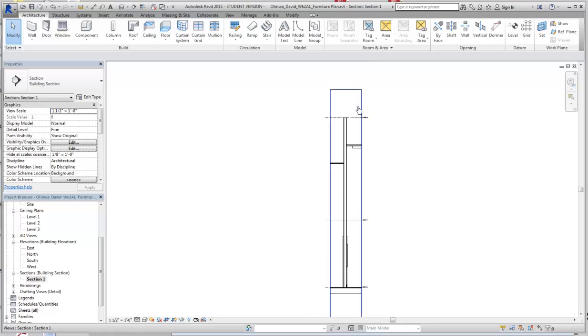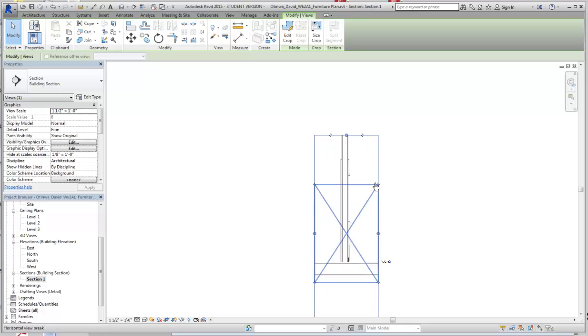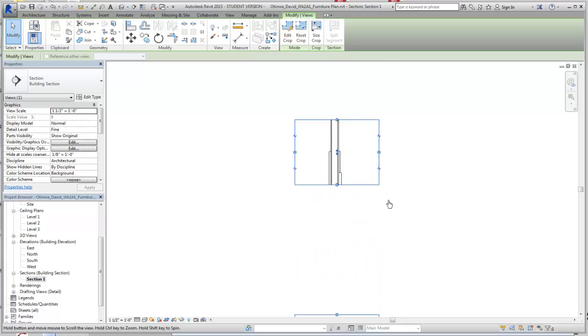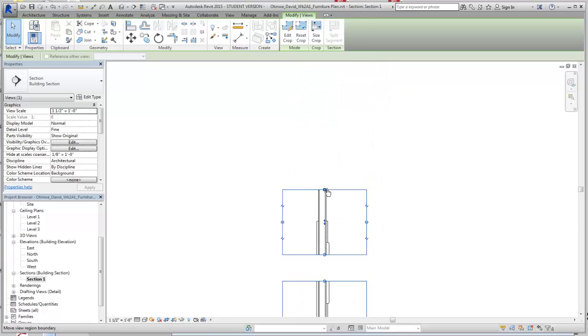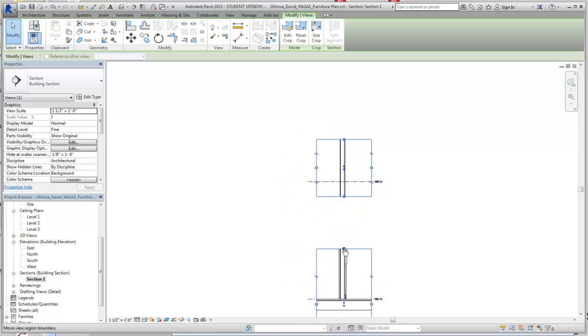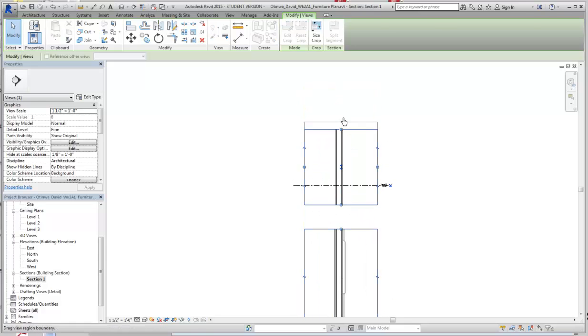Now we're going to say that our wall is not going to go up the whole way. So I can just go like this and crop it. Actually, you know what? I'll show you here. Let's do this first. So this right here is a horizontal break. If you need to do a break in the wall, so you show a portion and then not a portion, you can put that break through the middle of the wall right there.